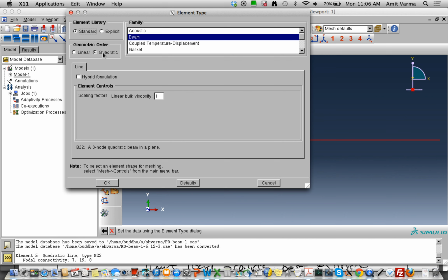How do I get that? Well, you remember your differential equation is fourth order, right? You get the fourth derivative of w with respect to x, d4w/dx4, is equal to 0. So if you start integrating, you get a cubic Hermitian polynomial for your displaced shape. So ideally, you should be using a cubic displacement function. I'm not using it, it doesn't even give me the option. The best I've got is a quadratic, right? So I'm going to use the quadratic. But remember, the Hermitian polynomial is needed for elastic analysis first. Secondly, it's used for the case where P equal to 0. So I'm not that worried about the fact that I'm using a quadratic function.